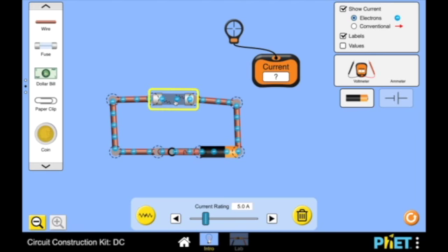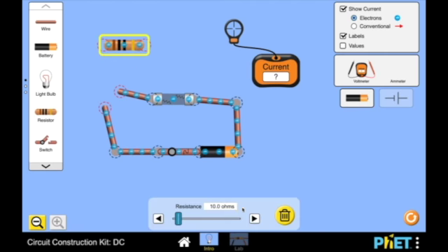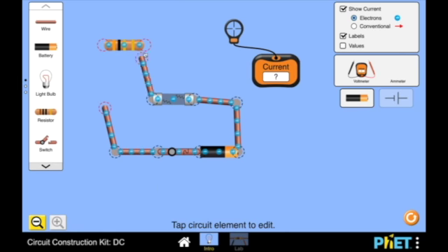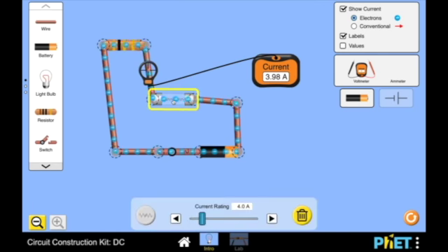So for that to be fixed, let's put this back to 4, and now we're going to take that resistor that we used earlier. Let's make sure that it is set at 3, and let's bring this in. Now when we repair our fuse, sure enough, we find because we have limited our current down, that even passing through here, it stays just under 4 and our fuse doesn't break.